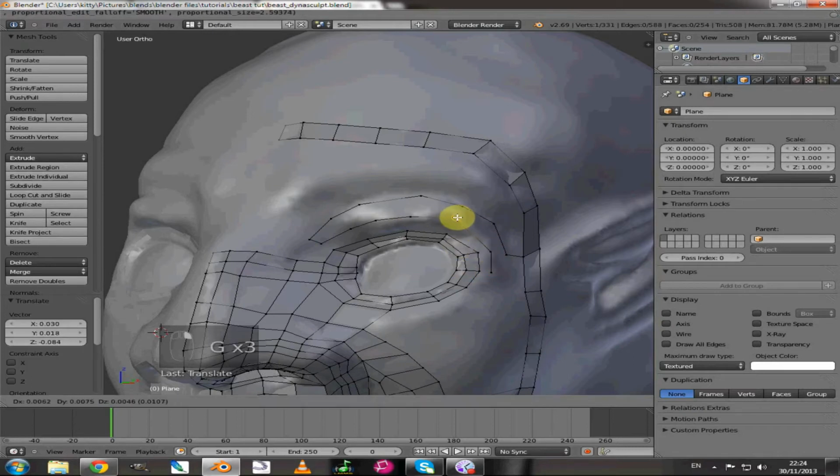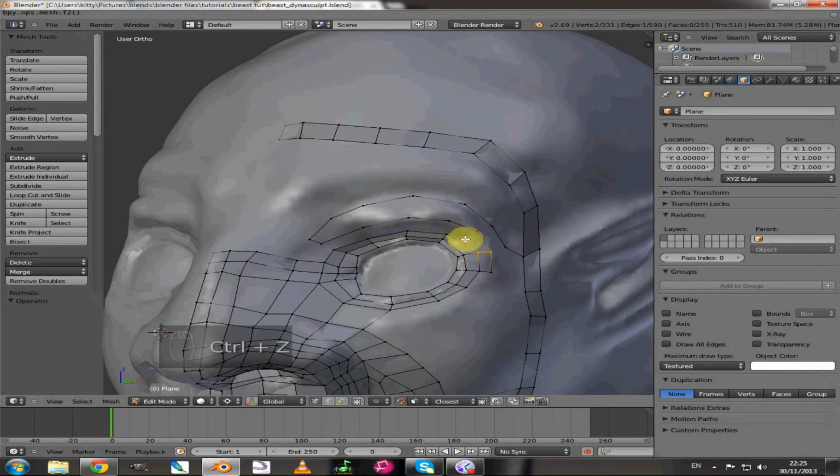Now make a double loop there and just rearrange the vertices I've made. I've miscounted somehow, because counting up to 5 is kind of tricky when you're working, obviously. I've just put in another loop cut to counteract that lack of vertices, and I'm putting loop cuts in by pressing Ctrl R.